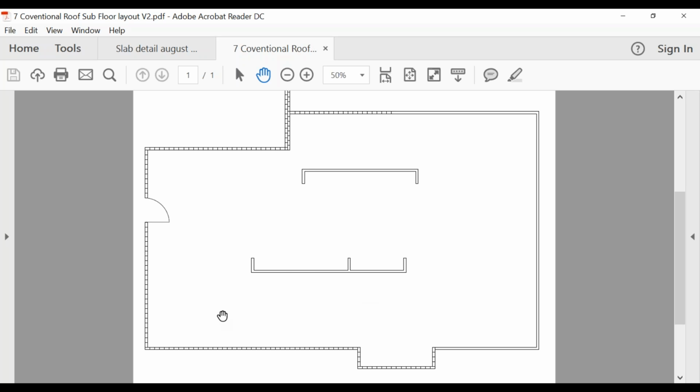So that's for when you're doing this little exercise later on tonight, if you get a chance, or on the weekend, if you work out your spacing. Ideally I always try and just put them straight underneath it and then put one through the middle and do it that way, but everyone does it a bit differently. But yeah, you can make sure it doesn't offset by that 1.5 times, and your bearer doesn't actually have to be directly underneath it.